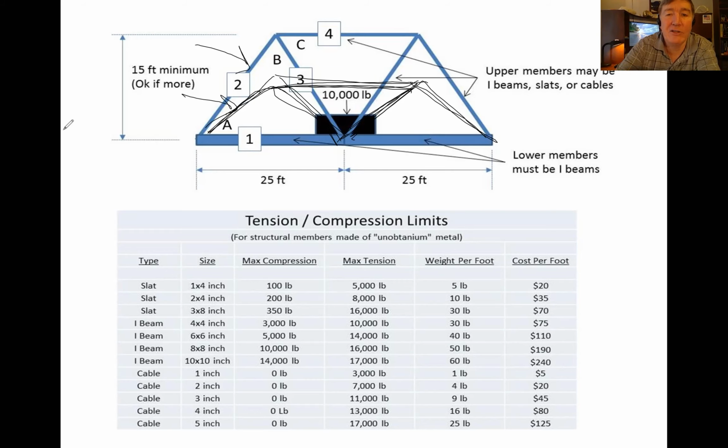And then that determines what the forces are going to be on the other side here, because the more the bridge weighs, the more this force is going to be. So you'd have to calculate how much the bridge weighs, and then calculate what these angles are going to be. And then when you add in all the forces, you can calculate how much force is in each of the members here. That's going to be a lot of work.